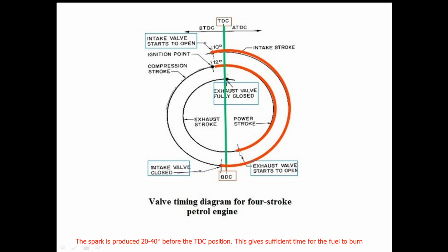Now, before the expansion stroke completes, theoretically, it should be completed at the bottom dead center. Before that, the exhaust valve will open. Exhaust valve will open before the piston reaches the bottom dead center. This is the exhaust stroke, and the exhaust valve will be closing after top dead center. Not exactly at top dead center, but after top dead center.